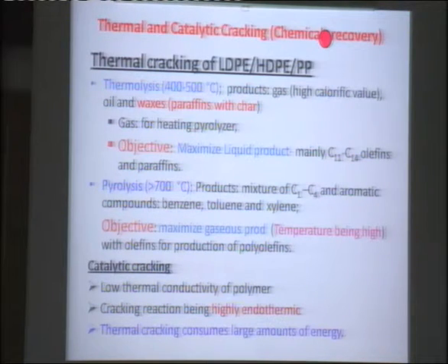Now these are some of the visualization experiments, just as I told you, for separating plastics from municipal solid waste. Municipal solid waste can be separated into plastics, non-plastics or other combustibles such as kitchen waste, and incombustibles, for example glass, wires, metals and all such things. Then they can be utilized for different processes. As I told you, PVC should not be used for incineration along with polyethylene and polypropylene, because it produces hydrogen chloride, which is highly corrosive and forms different types of toxic products.